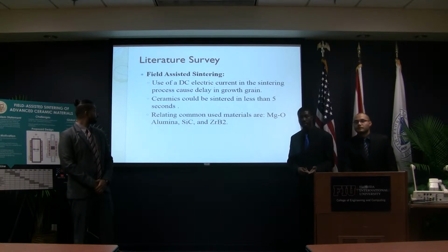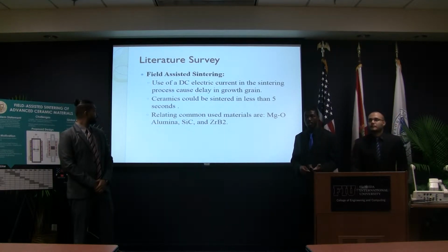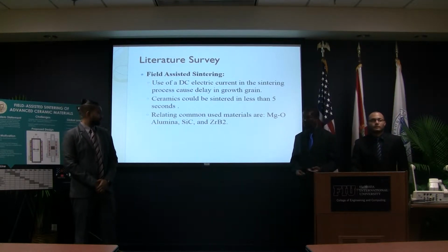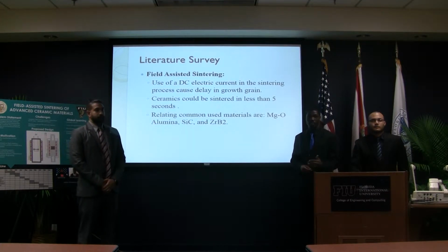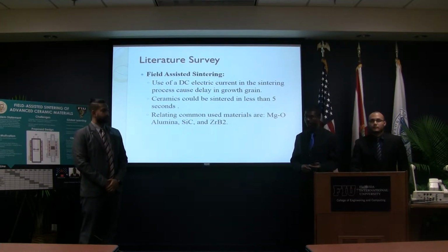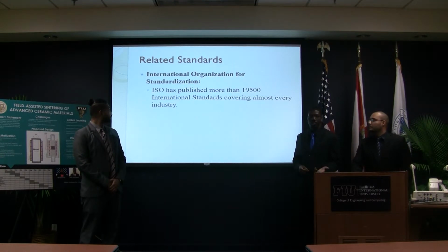During the literature survey, we found that applying a DC current to a ceramic powder while it's in a furnace will allow for densification within 5 seconds. That's why they call it flash sintering. In conventional sintering, it takes upwards of 24 hours.